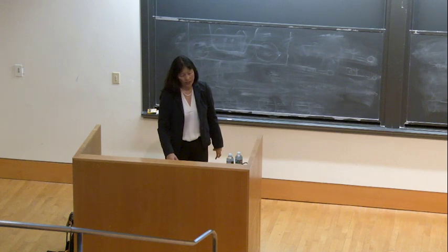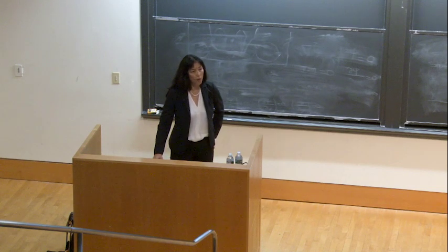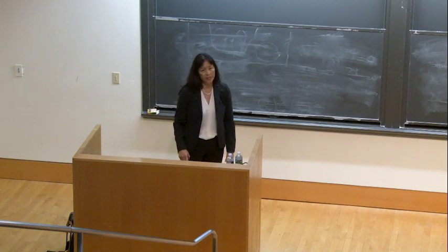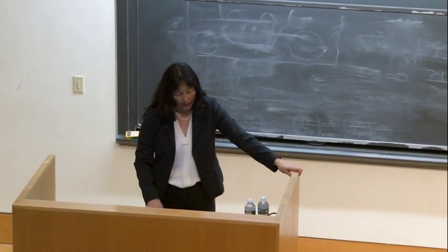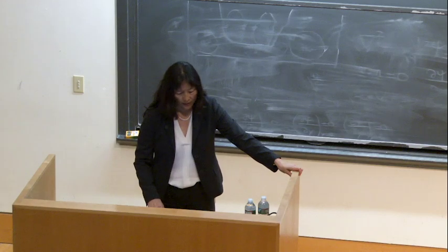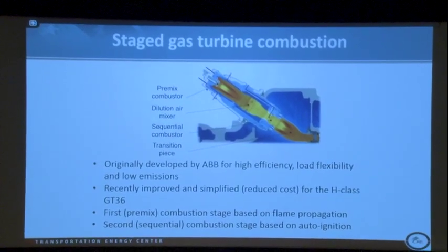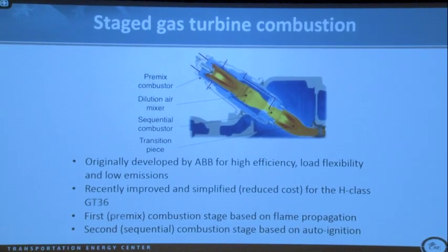Hydrogen is also quite energetic, and so it generates very high heat release rates, and that can couple with the acoustics in your combustion chamber and generate unwanted thermoacoustics and noise that can amplify and damage your engine. So these are some of the challenges. Just to give you an idea, one concept that has become popular recently is looking at staged gas turbine combustion with reheat. This is a concept that was originally developed by ABB, gas turbine manufacturer, for high efficiency load flexibility and low emissions.